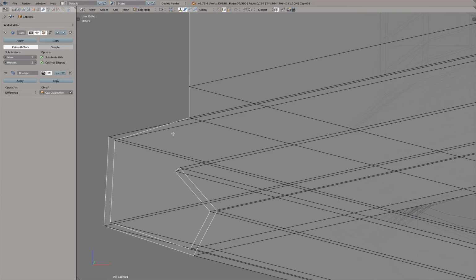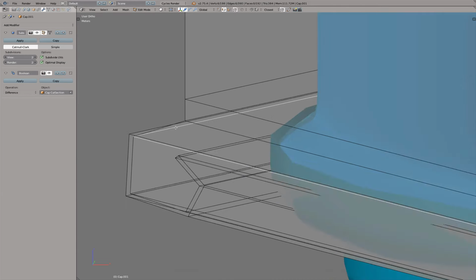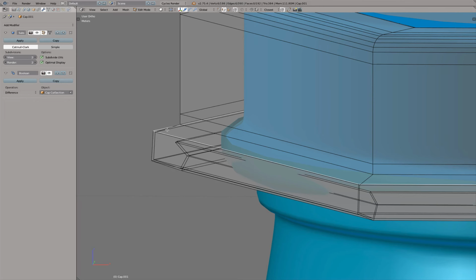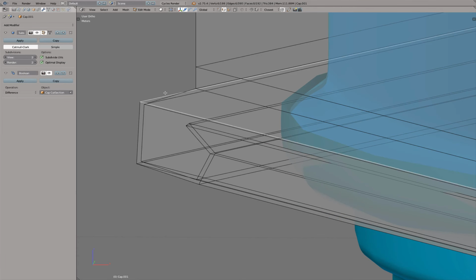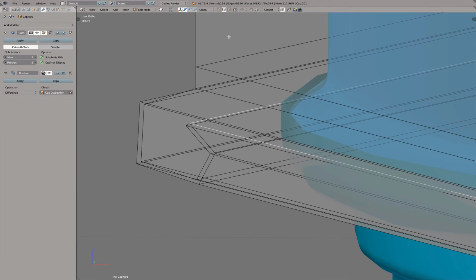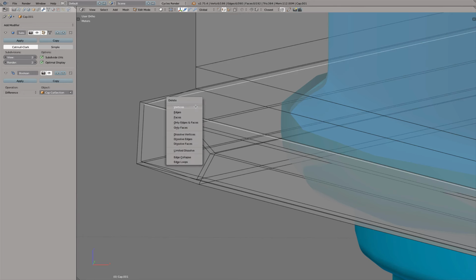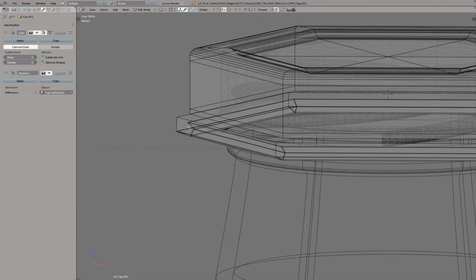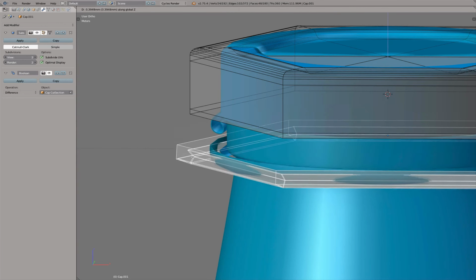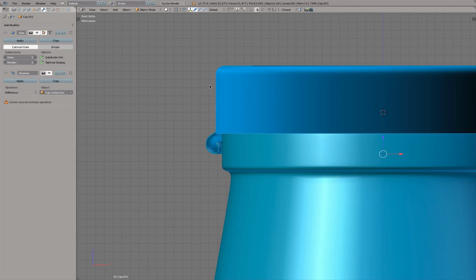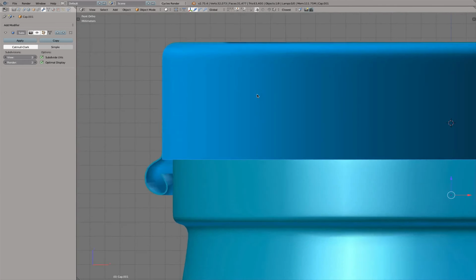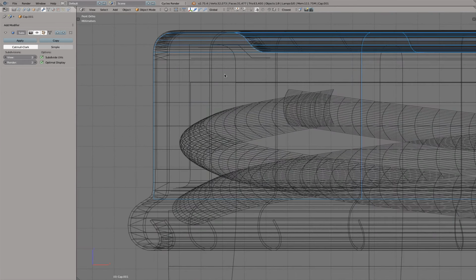And then here, this inner loop I would like to select. Sometimes you see I have some issues selecting the cuts. Then maybe you can turn this one off, then you can much better select through objects. This actually prevents selecting through an object. This we delete, and you see we have now this left over, and we can delete this. Perfect. Now the Boolean command obviously will complain.